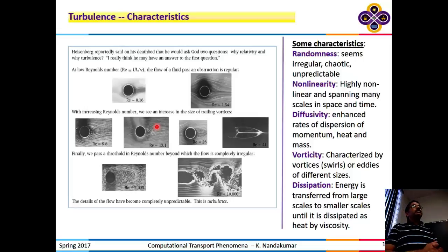This problem is still interesting, and we just had one PhD student from Australia that worked with us who did the simulation for Reynolds number of up to 2000 in a freely moving body. This was a fixed sphere. Okay? But if the sphere is settling, what happens? The sphere starts moving in a very random fashion because it experiences both drag force and lift force that will move it sideways. And there are a lot of fascinating experiments that have been done in the last 20 years or so, providing us the data for validating our DNS kind of simulations.